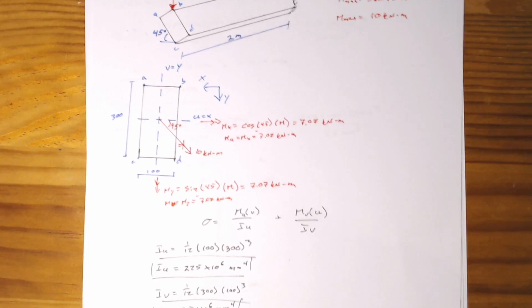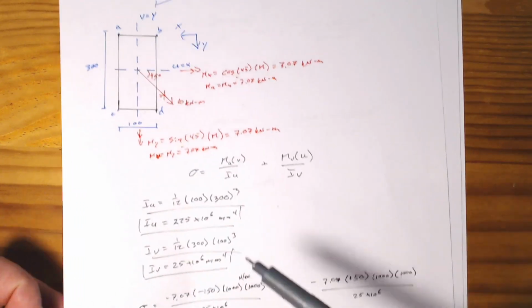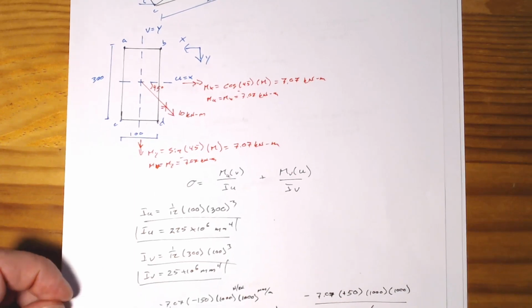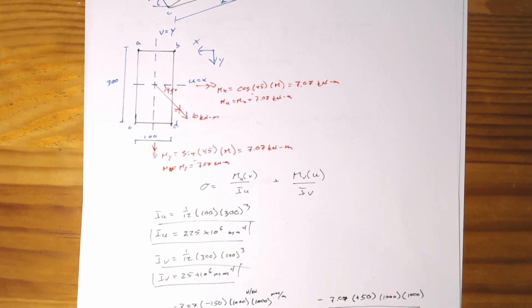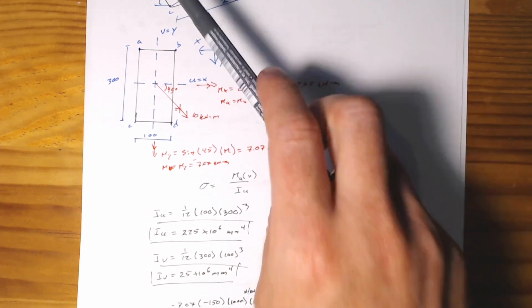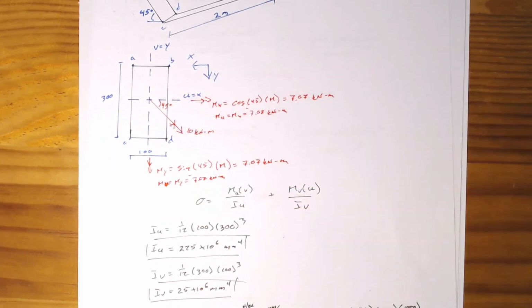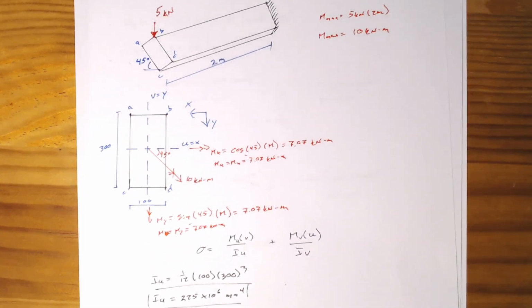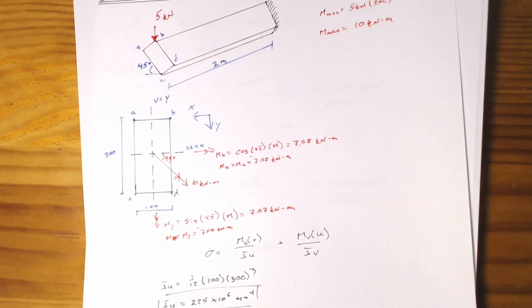I can use that to double check that I've got the correct sign on my moments and the correct sign for my coordinate system. Without that, I find it personally quite confusing, and I'm sure many of you will too. So the big trick on this one is to think about what's actually getting bent around the structure, and don't just blindly apply these equations. Then you should always be quite fine.